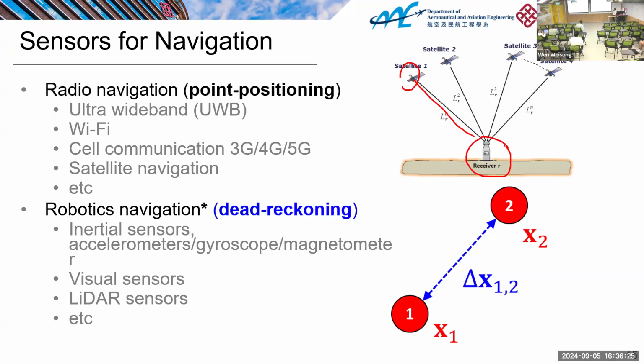The second one is called dead reckoning. Dead reckoning only provides relative information, for example, from inertial measurement from an IMU. So what can the IMU provide? For example, in smartphones, we have IMUs, right? An IMU can provide linear acceleration and angular velocity. Angular velocity means the change. It can only help you infer the change of your position or velocity.